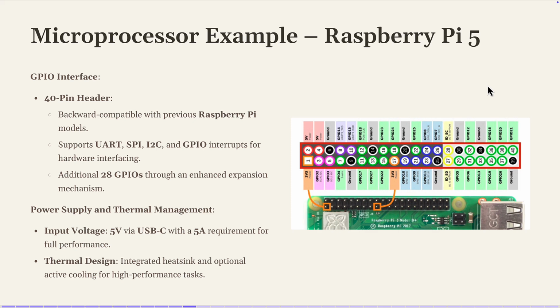Okay, and it even has thermal management. Usually when you run a sophisticated application like AI or deep learning, the board will be heating. So we can attach a heat sink that will absorb all the heat that comes out of the board. If you don't do that, you can damage your component. So when you have a very complex application that will run on the board, it's better to have a heat sink, okay, for active cooling and high performance. So usually it comes with a fan to keep the board always cooling. Usually these boards will have much lower performance if they become very hot.